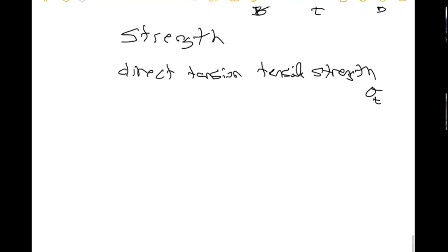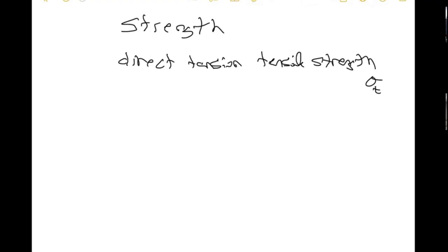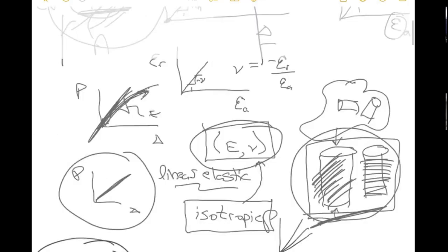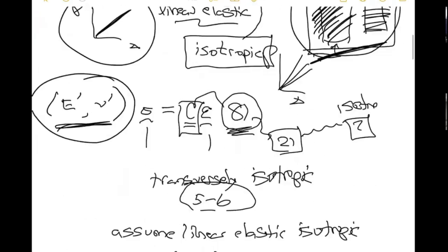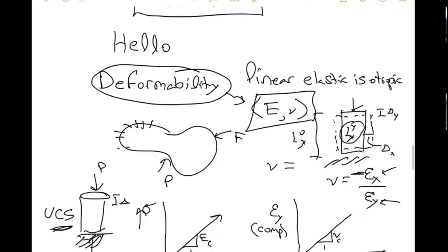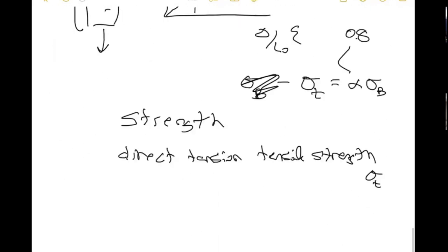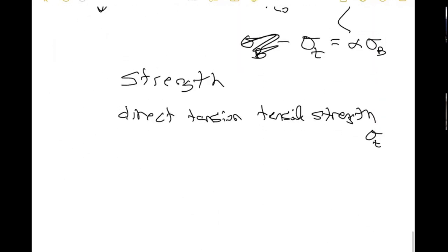In general, in most rock mechanics situations, there's not very much data. It's quite expensive to do tests. And oftentimes it's even hard to get the material out intact. Oftentimes when you drill out the material, it damages it in the process of taking the core.